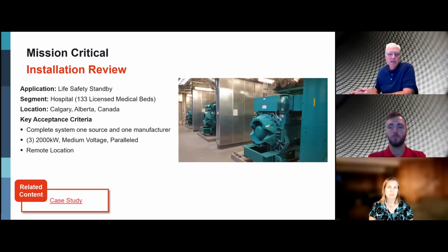A separate building allowed better airflow for cooling, and reduced noise pollution as gensets were enclosed in separate quarters from the main campus. Vibration was also not a concern on adjacent floors, as it didn't apply. The remote location also improved maintenance and service schedules, as access was easier in lieu of negotiating above grade or below grade floors in normal hospital applications.